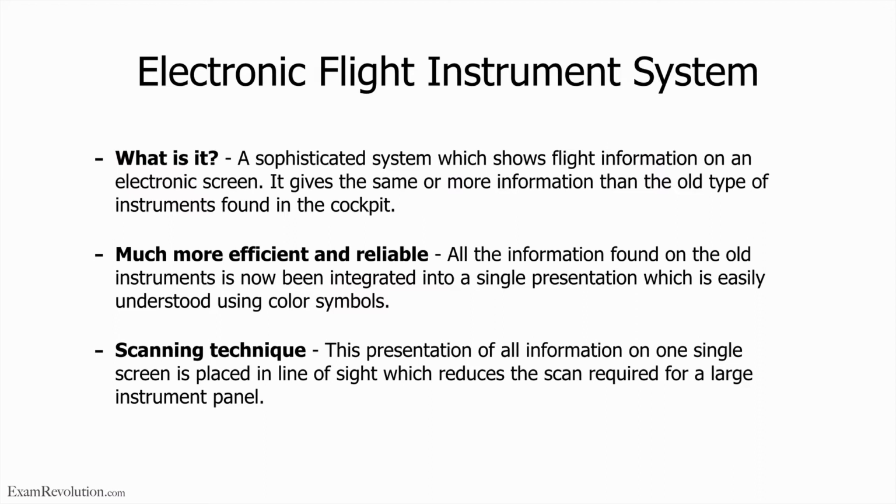So obviously you'll have different screens for your engine parameters and for your air data, like your airspeed and your altitude and your attitude, but the principle stays the same. All your air data will be incorporated on one screen close to each other, and all your engine systems and flap systems and undercarriage systems and all of those things, basically the aircraft systems, will also be shown on a separate screen. It depends on the aircraft type and it changes from manufacturer to manufacturer, and also obviously depends on the type of avionics that you've got, but that's how they are typically split. It's typically split into your air data like airspeed, altimeter, your AH and all of that, and then another screen has got all your engine parameters, your flap settings, whether your gear is down or not, all those things, right?